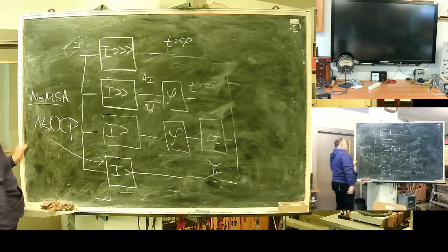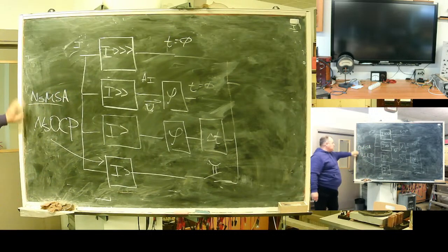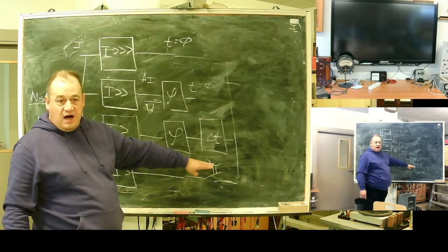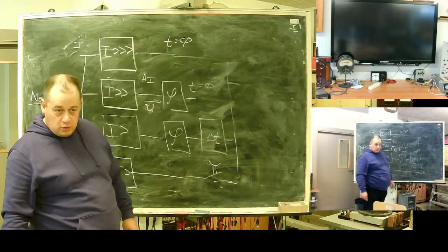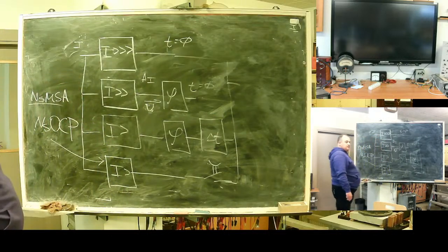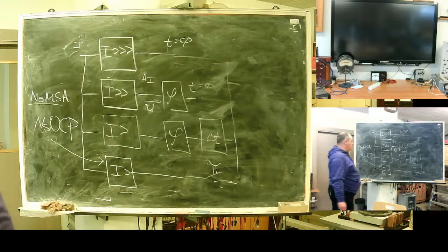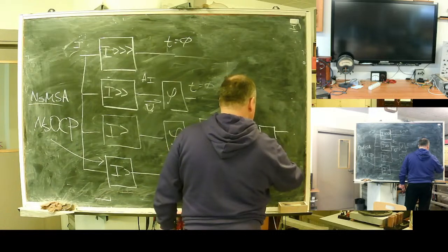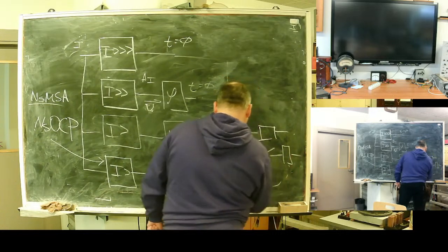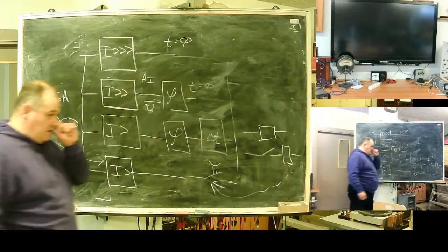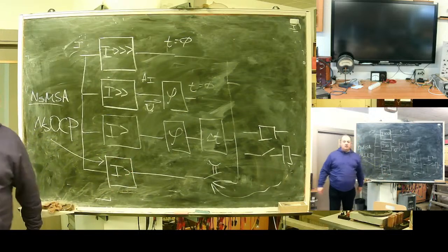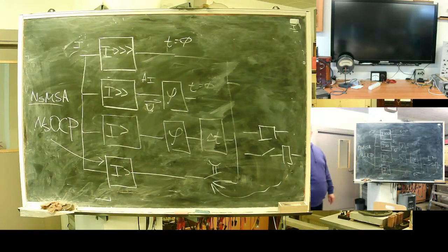In Latvian, NSMSR, neselektīva maksimāla strāvas aizsardzība. Non-selective overcurrent protection, activated for time up to 1 second after the switch is turned on. Actually this stage acts only in switch on fault conditions.